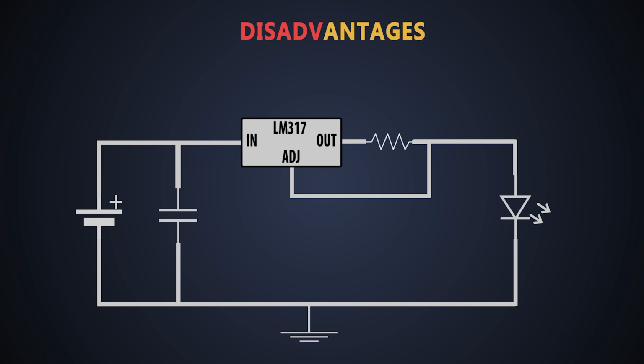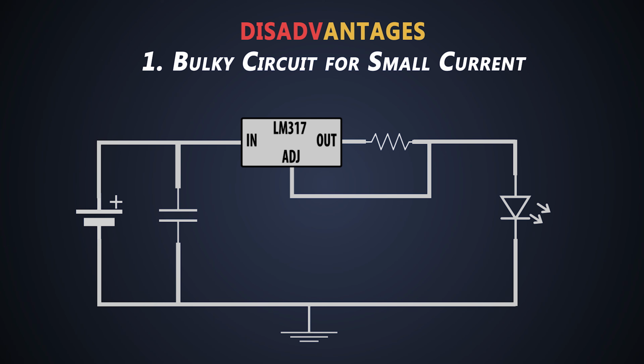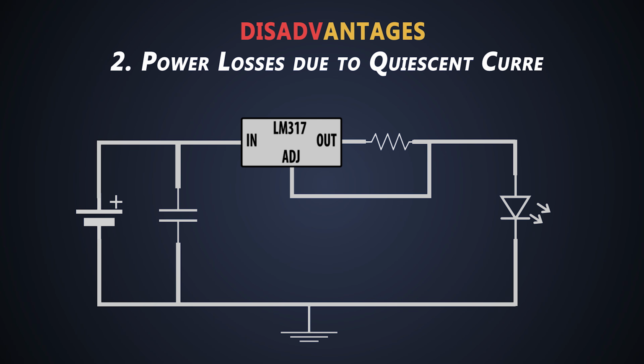But there are some limitations also. For small current applications, this regulator might be very bulky. Due to quiescent current from regulator, there will be some power losses.